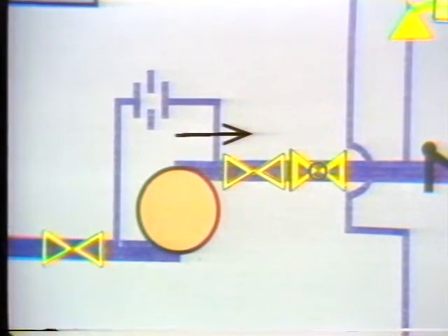In this case, the shape of the symbol for the pumps helps to show which direction the discharge is. But if the symbol were a simple square or circle, basic engineering practices tell us that we throttle the flow from a pump at the discharge of the pump. So, if we look for a throttling valve, a globe valve, we know that is the discharge end of the pump. Now, there's another valve that will show the direction of flow through a system, the check valve.